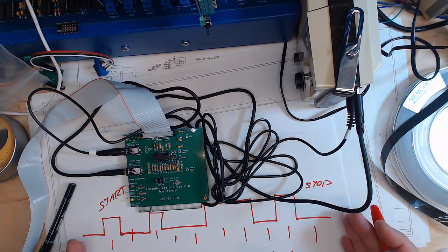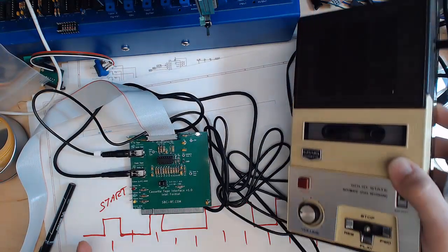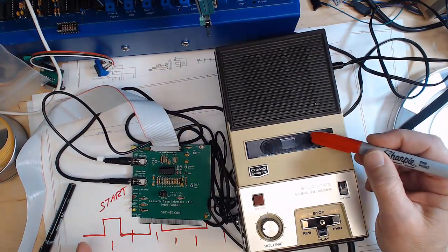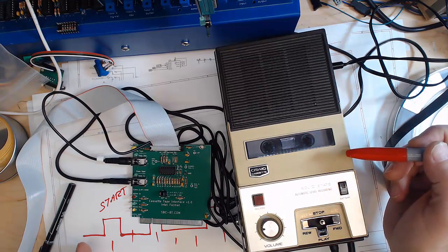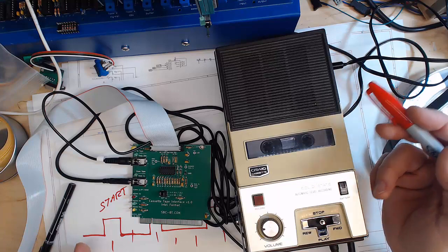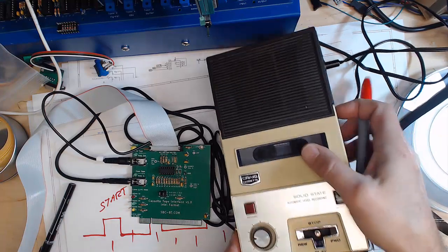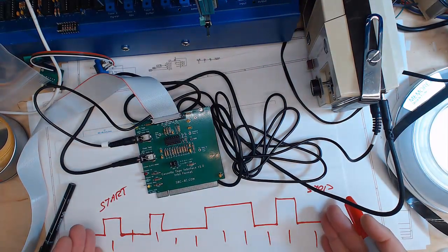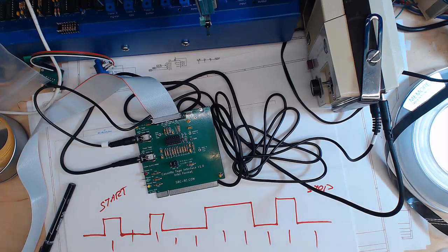So the fundamental problem is that when we're playing a tape, sometimes you would see on a take-up spool it would get a little bump on it, and so the tape would jump across that, or the tape gets a little bit worn, or your batteries run down, or the tape is going faster or slower, its speed control isn't all that great. The problem is it becomes impossible to time this. It's just as if your baud rate were off. All of a sudden you would start getting junk on your tape.